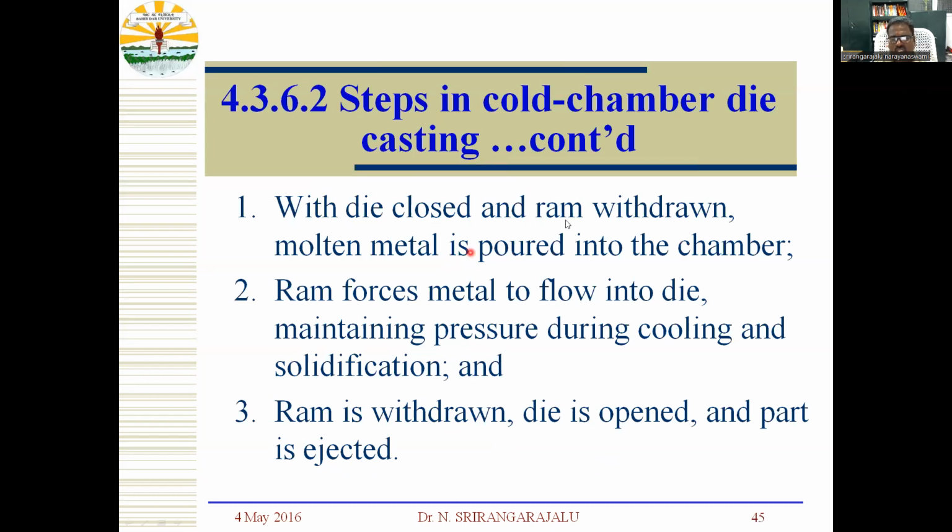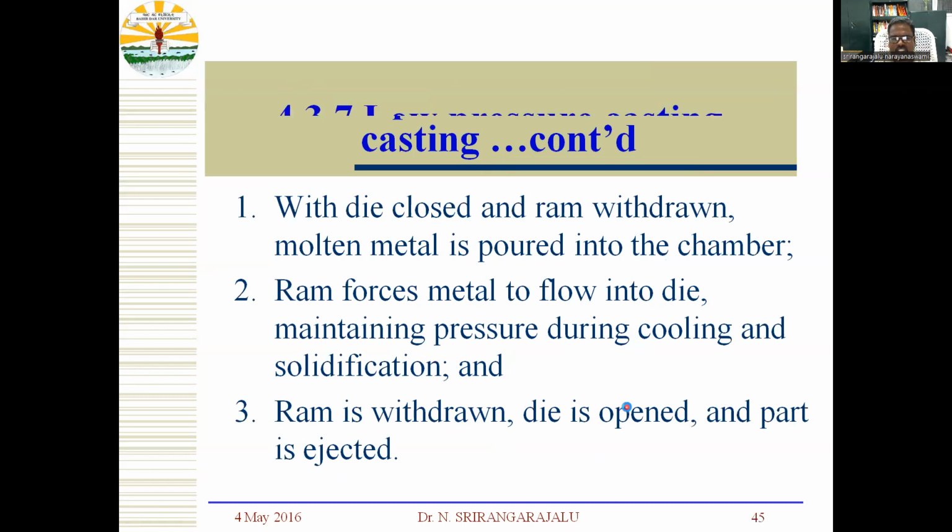With the die closed and ram withdrawn, molten metal is poured into the chamber. The ram forces the metal to flow into the die, maintaining pressure during cooling and solidification. Then the ram is withdrawn, the die is opened, and the part is ejected.